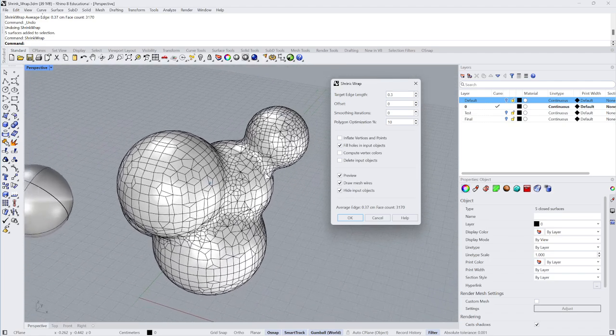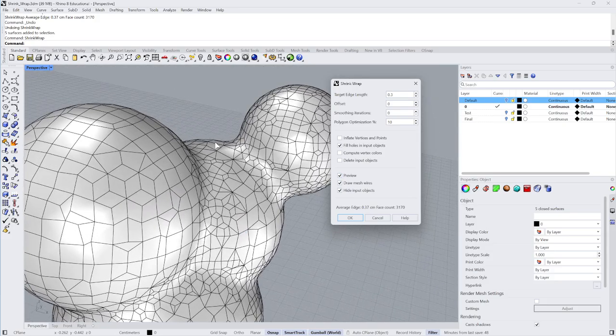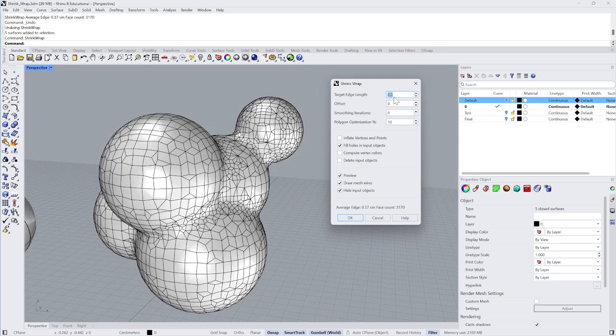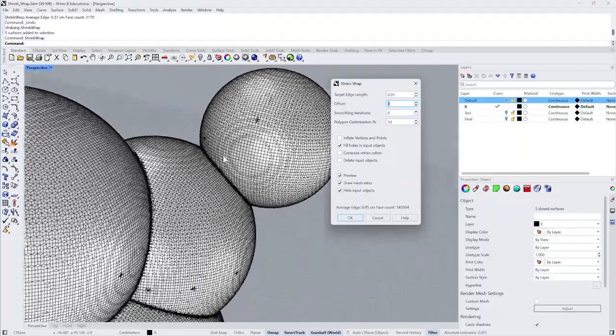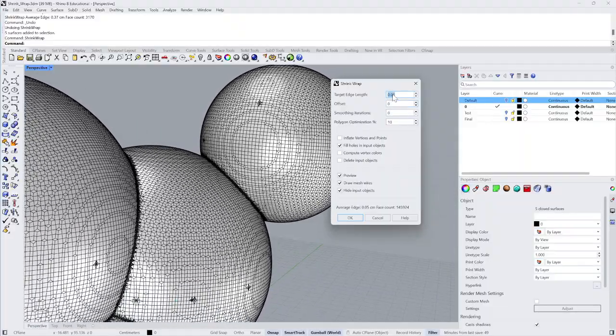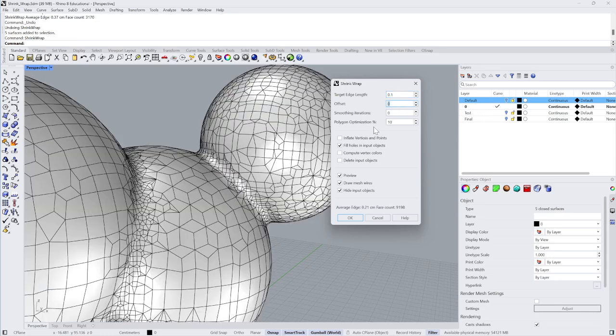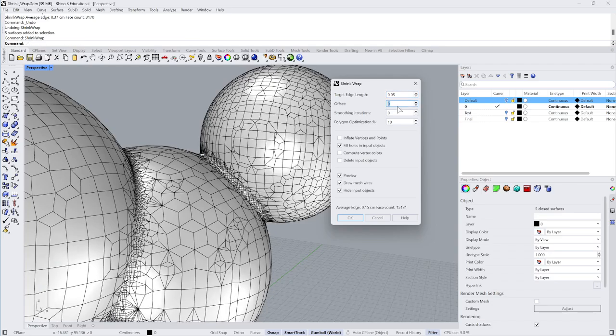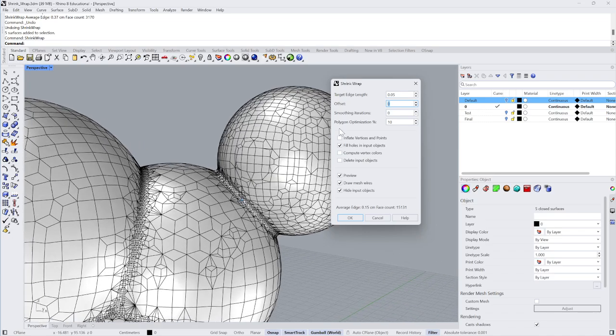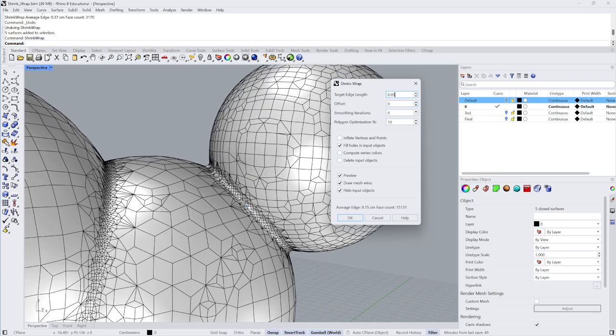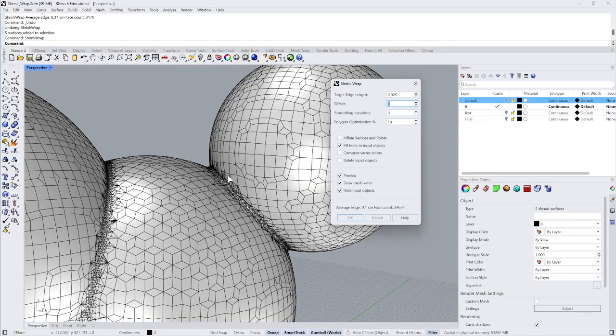The difference here with the original one is that we're getting some smooth transitions, which is kind of nice. If you don't want those, then what you need to do is lower the resolution of the mesh, take this down to something like 0.01 and preview that, and then you can see that you're getting a really tight seam around here. That's pretty intense. So maybe we want 0.1, or we could have 0.05, something like that, and it gets less heavy, but we're getting a sharper seam there.